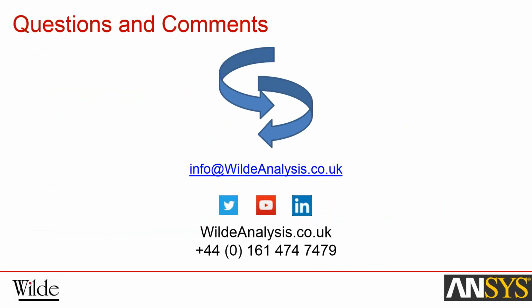Yes, and I'm actually using dynamic mesh quite often nowadays for in-cylinder type applications and for FSI, for two-way FSI. Because the solver itself is more forgiving of the mesh that comes in, you will have better luck with version 16. Back in the day, something that possibly didn't work in a version of Fluent could work in CFX, but now they're pretty much the same because Fluent is more forgiving of your mesh.